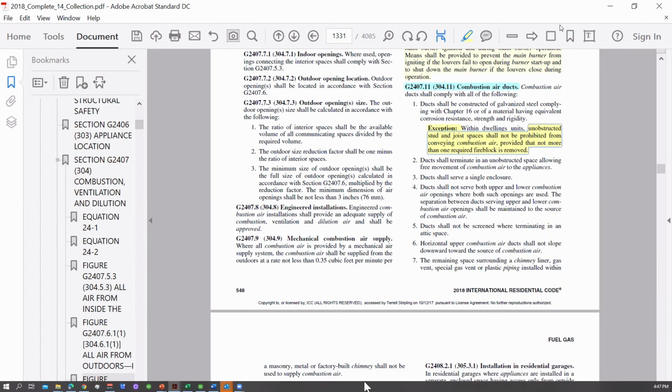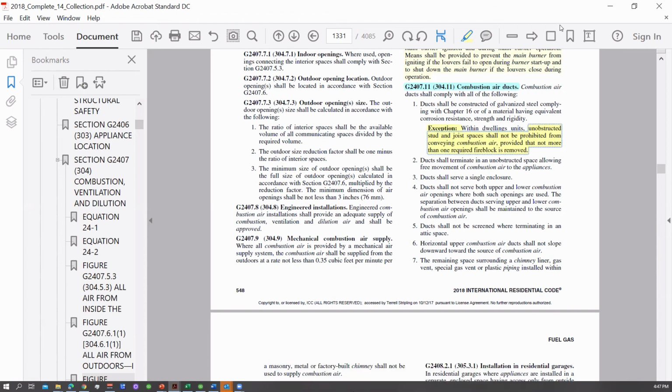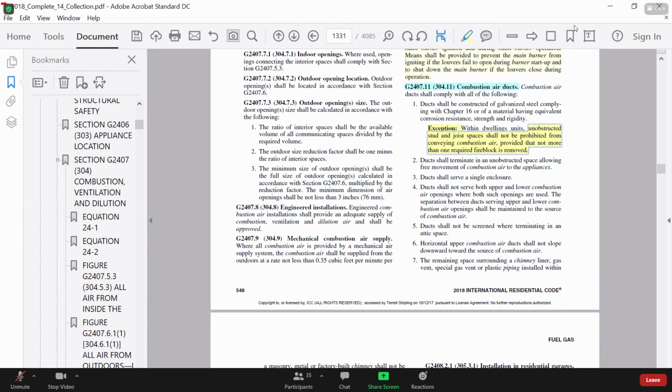Just a comment on that, Jerry: the energy code calculations, we should have to check, allow a certain amount of non-complying area, particularly with windows, but it could be used for this. You would have to be within that allowance. We sometimes have that happen in remodeling, and they'll put it on an exterior wall and want to use the trade-off for the whole cavity.